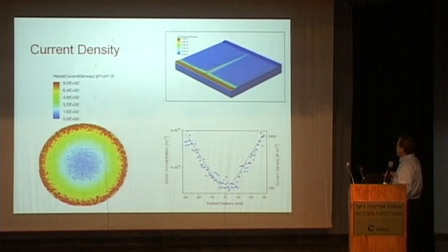So we have a very strong diffusion. And what this implies, if we have such a very strong diffusion of dopants, here I plot the dopant concentration across a wire. So the solid line is the donor concentration from one side of the wire to the other. So you see a drop of almost 2 orders of magnitude.